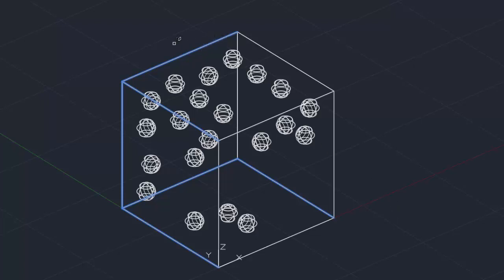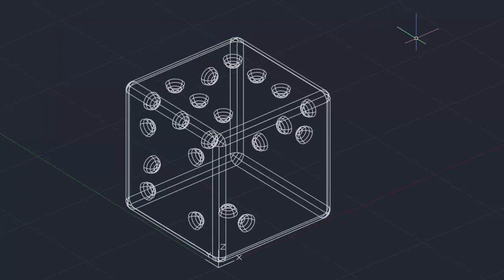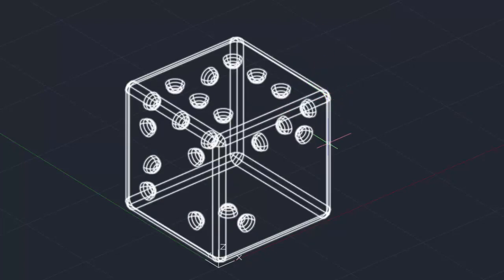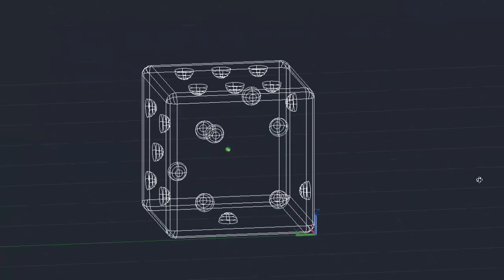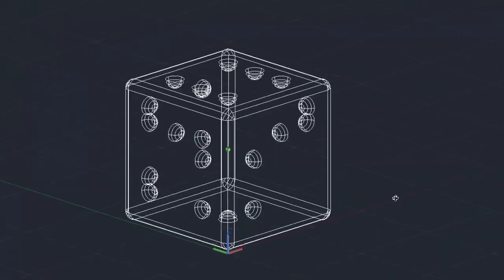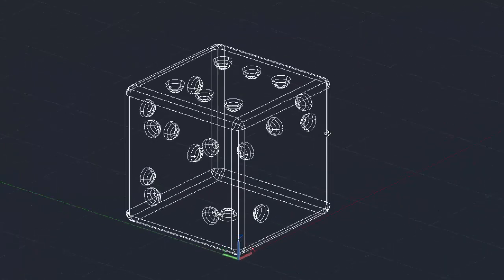Now, by that, I'm saying just treat this as a back face, treat this as a front face, and then each of the lines between them, we make sure we select them all, then hit enter, and everything will fillet. If you miss one, it's not a problem. You simply just redo the fillet command, select the individual one, and then hit enter, and it will put them in. Or you can do a chain command as long as they are touching each other, and then put them in that way. But what you need to end up with is that whole filleted die with the dimples.